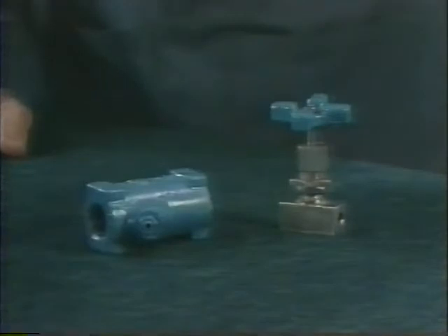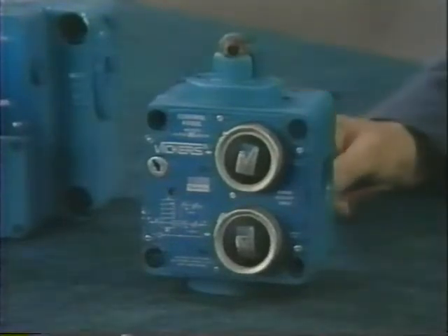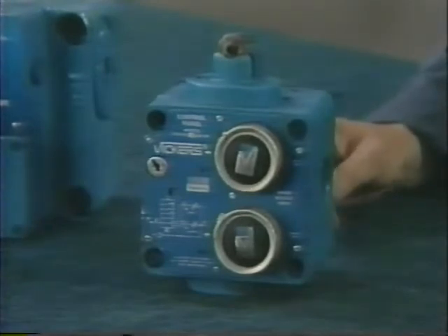It's installed in the circuit by means of threaded pipe ports. Now this is the unit that's both pressure and temperature compensated. The knob on the front allows us to set the throttle opening, and the key is a means of locking the setting. The valve is installed into the system by means of a subplate which has matching in and out porting. Over here we have a feed control panel, which in effect is two flow controls. This package allows the cylinder to have a rapid advance and coarse and fine feed cycles. It too is installed into the circuit by means of a subplate. No oil lines are connected directly to the valve body.